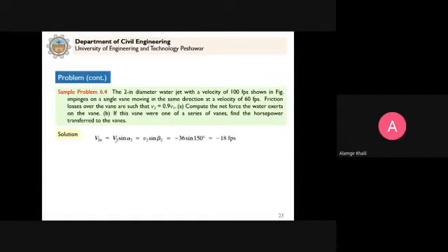And in the vertical direction, V2 sine alpha 2 will be equal to small v2 sine beta 2. Whatever the shape of the triangle, these relationships are always true. In that case, this is equal to minus 18 foot per second. Clear? The negative will only show the direction.